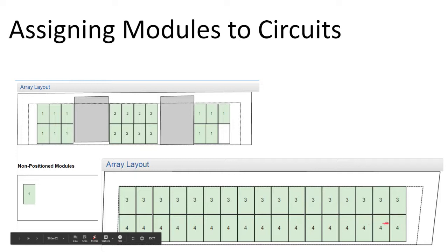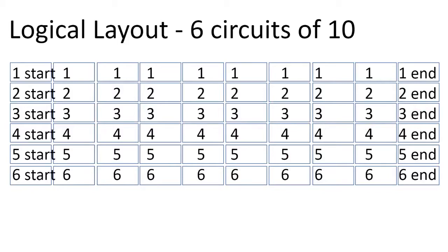Now that we know the number of circuits the array will have, the next design step is to identify where the starting and stopping point of each circuit will be. This information is useful in determining where the home run circuits between the solar array and inverter will land up on the array on the roof. Special care should be taken during installation to make sure these circuits are plugged up correctly. Having these locations planned carefully in advance will reduce mistakes in the field. I locate these connections at the corner of an array so that if they ever need to be inspected in the future, they are easily accessible.